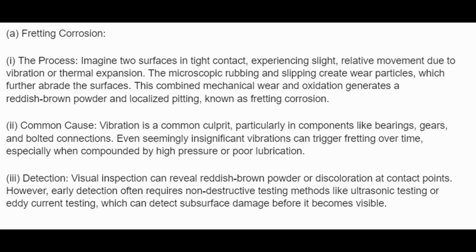3. Detection. Visual inspection can reveal reddish-brown powder or discoloration at contact points. However, early detection often requires non-destructive testing methods like ultrasonic testing or eddy current testing, which can detect subsurface damage before it becomes visible.